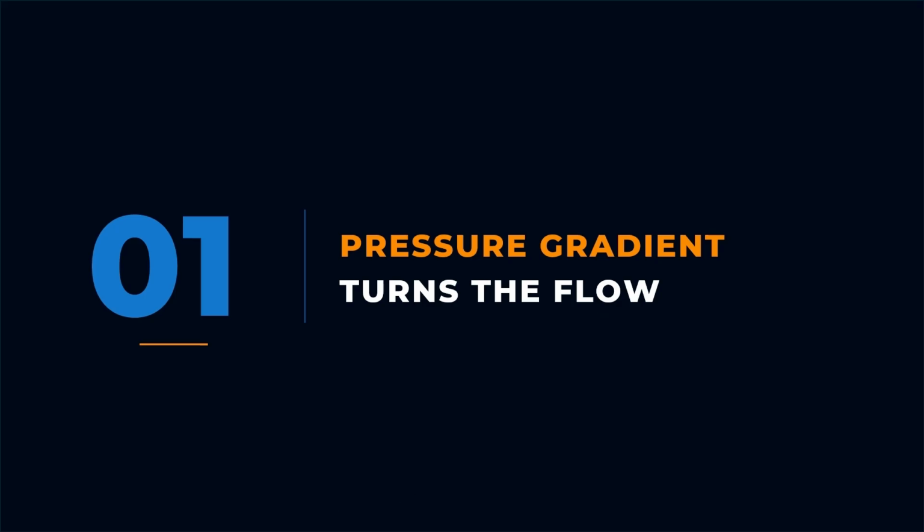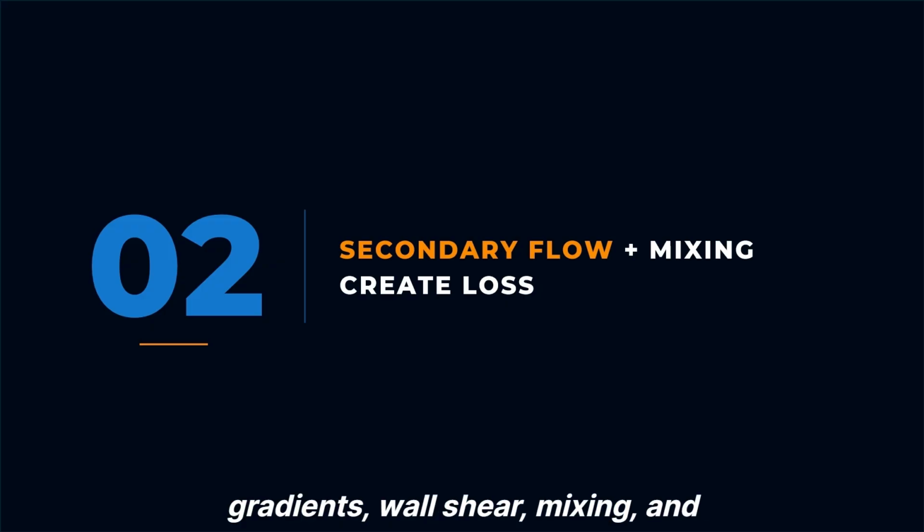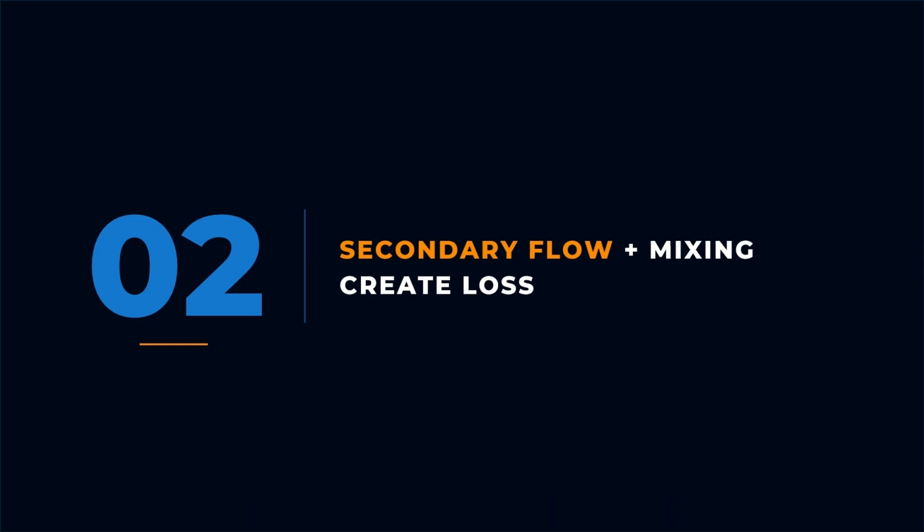Takeaway 2. Number 2. The irreversible loss comes from real fluid effects. Secondary flow, increased velocity gradients, wall shear, mixing, and possible separation all contribute to additional hydraulic resistance.